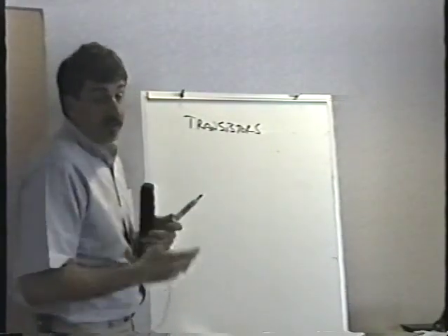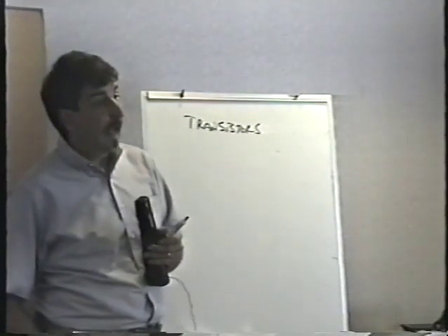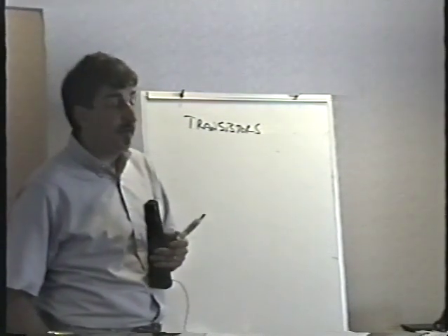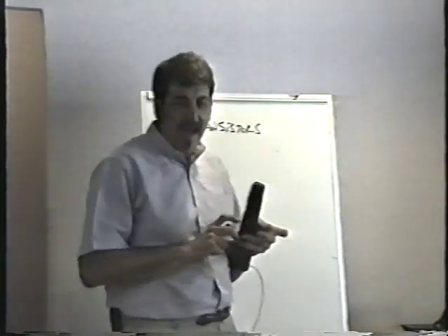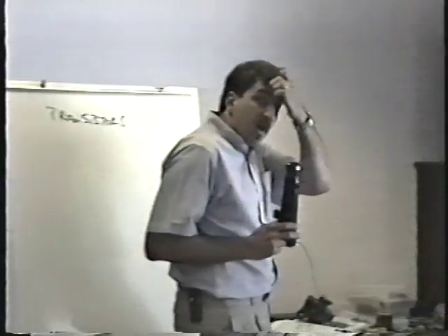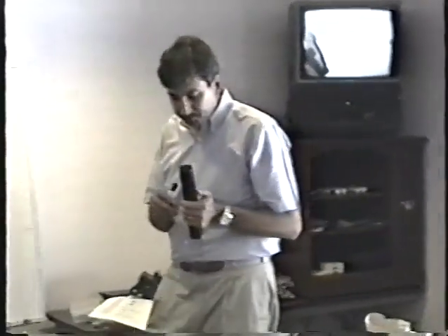I see lots of transistor failures, especially in power supplies and monitors and pinball machines. Very common. Much of the time, if you have a problem that's not a capacitor, you have a semiconductor failure, and transistors are real common failures. I see lots and lots of transistor failures.